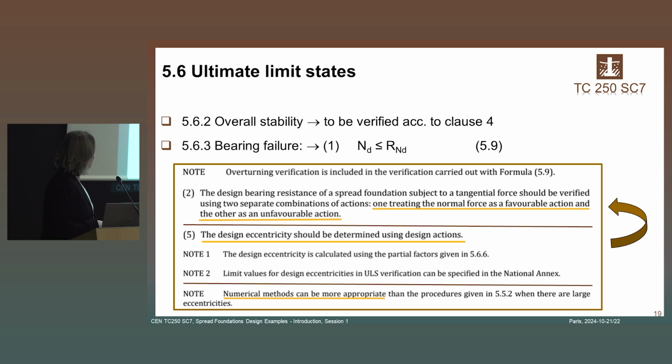You should consider if you can apply the regular bearing capacity equation, because it has been established for a moderate eccentricity, and the concept with the effective width of the footing is not suitable for large eccentricities. So in this case, you may use numerical methods instead, like FEM analysis or something like that.